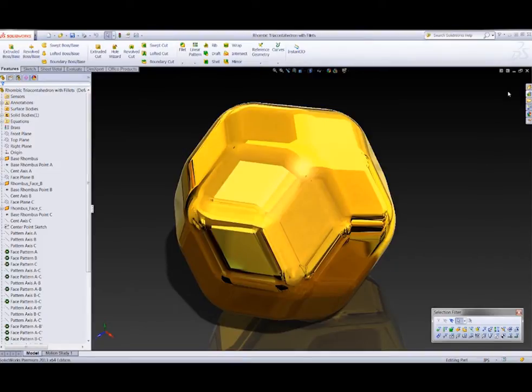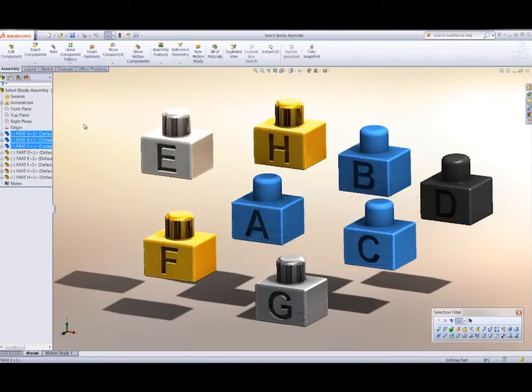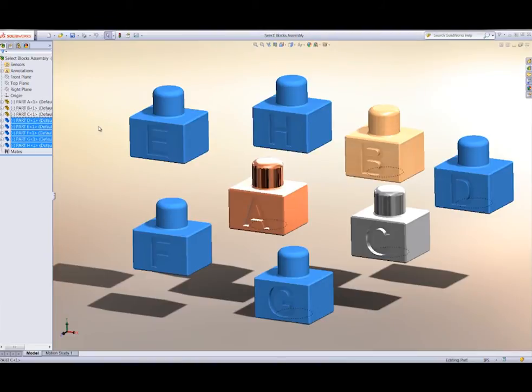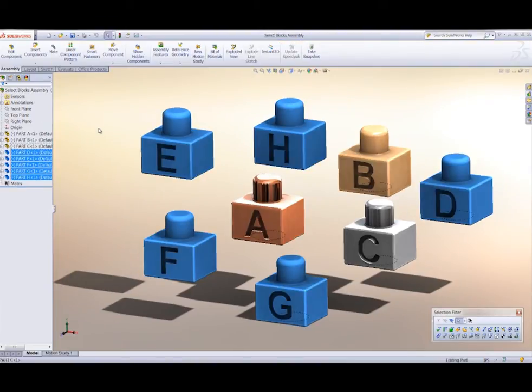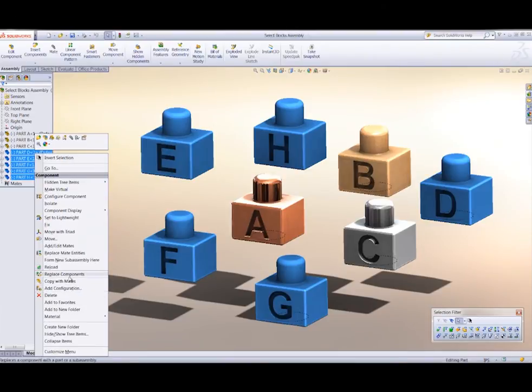One place the Invert Selection tool becomes a whole lot more handy is within the assembly environment in SolidWorks. Here we have, I guess, a non-typical assembly of my lettered blocks. And if we grab a couple of these blocks and use my keyboard shortcut, Control-Shift-I, we have the alternate blocks selected. You're then free to go ahead and perform whatever actions you need to onto those objects.